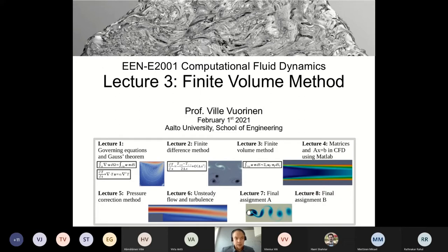But the finite volume method is, we have conservation laws, and it's particularly easy to simulate conservation laws, to conserve something, with the finite volume method. The reason for this is that we have the Gauss theorem, and that's related to these conservation laws as well. So, long story short, it's a compact method to solve conservation laws, and this conservation property is built into the method quite naturally. You can build it into finite element methods, but things are much more complicated that way, in my opinion.